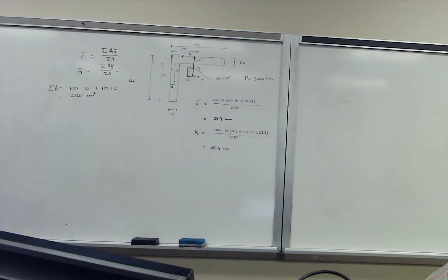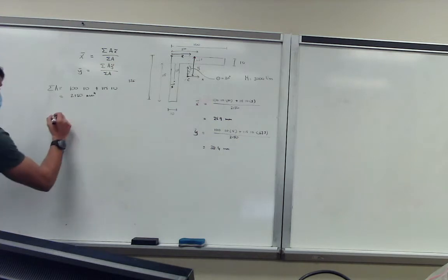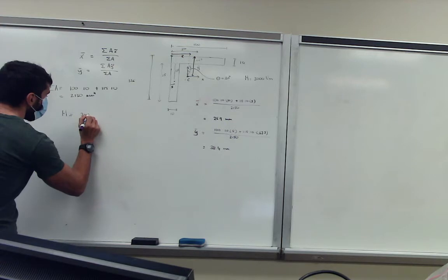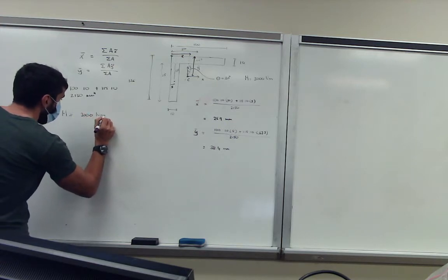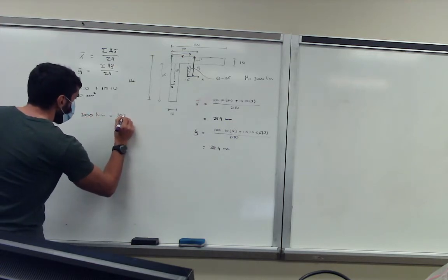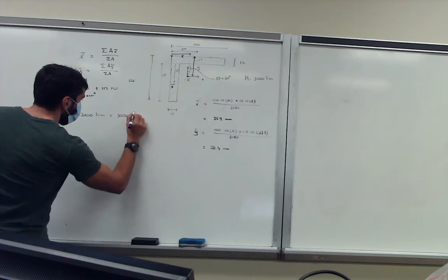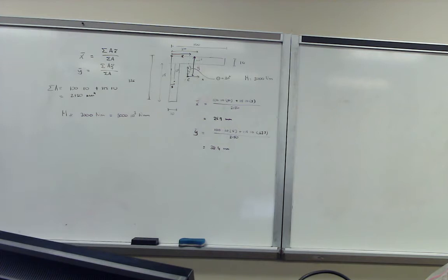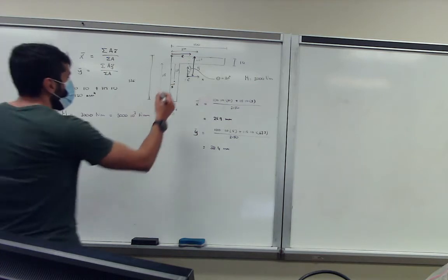In thin wall structures, you reduce the thickness, but in this case we don't reduce it. So another point is, okay, let's find our moment. We have a given moment, and that's 3,000 Newton meters. And always useful is just to convert it to the same unit as your moment of inertia. So it's 3 times 10 to the power 6 Newton millimeters, and that's basically acting in this direction.